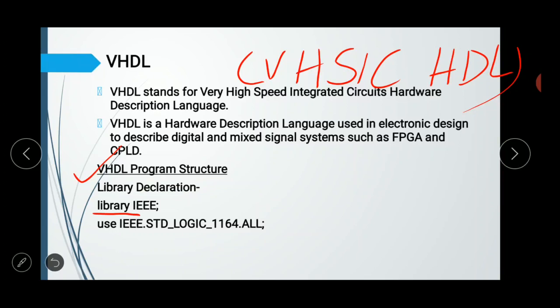There are three libraries usually used in all VHDL codes, that is IEEE, STD and work. So IEEE specifies multi-level logic system. STD is the resource library for VHDL design environment, and work used for saving our project work and program file. But in program code, we need to declare only the IEEE library, because the other two libraries are default libraries.